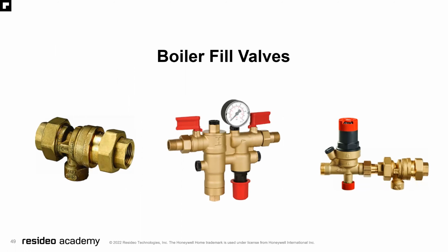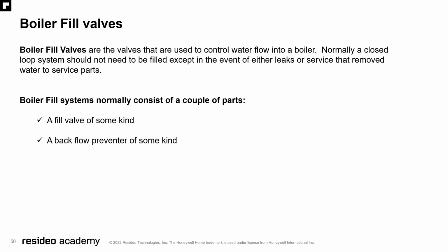Boiler fill valves. Boiler fill valves are the valves that are used to control water flow into a boiler. Normally, a closed loop system should not need to be filled except in the event of either leaks or service that removed water to service parts.